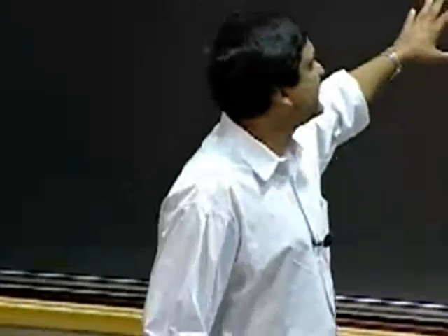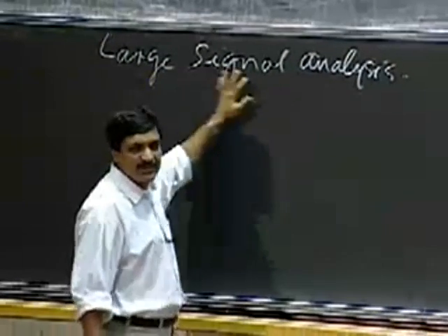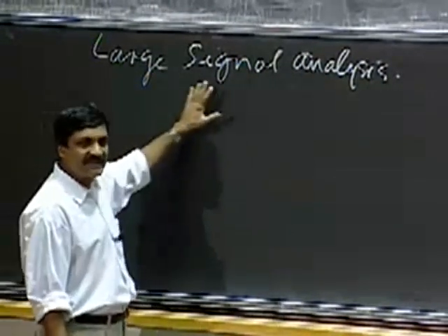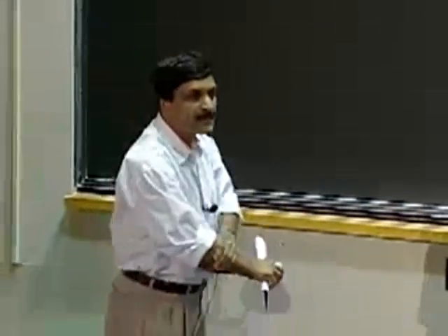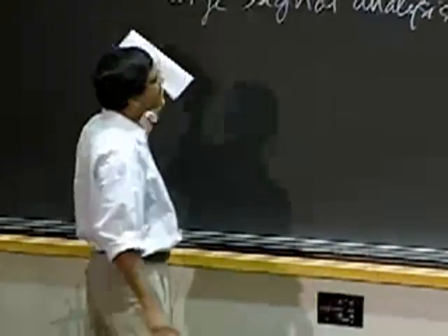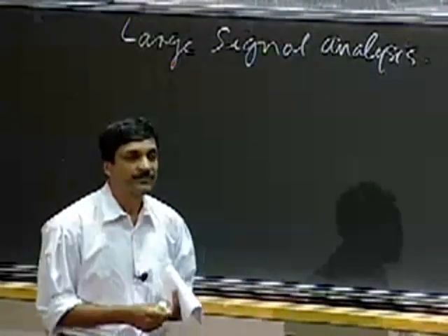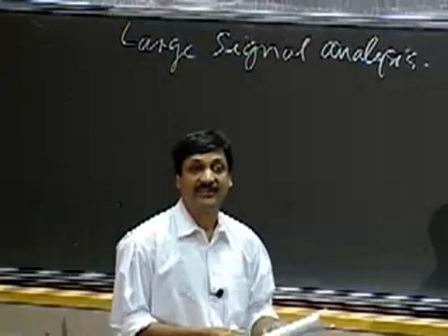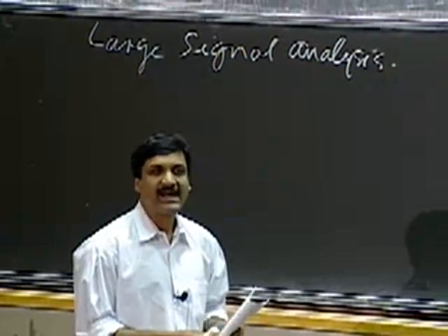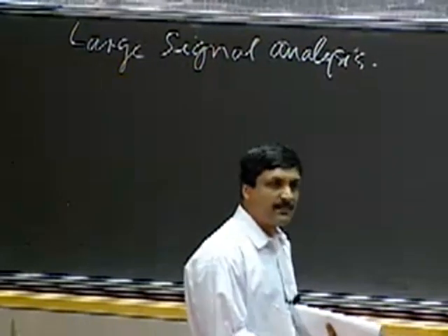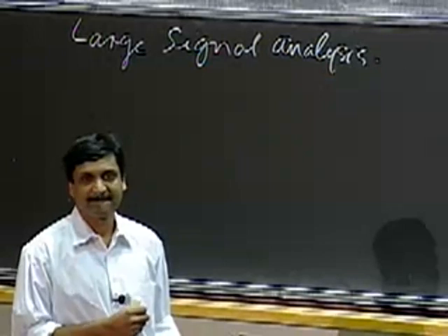What we're going to do today is called large signal analysis. And this is a loaded term. Large signal analysis means something very specific in our business, and I'll describe to you what that is. This analysis involves looking at a circuit containing, for example, a MOSFET, and figuring out how to get that device to operate in a way that the MOSFET was always in saturation.